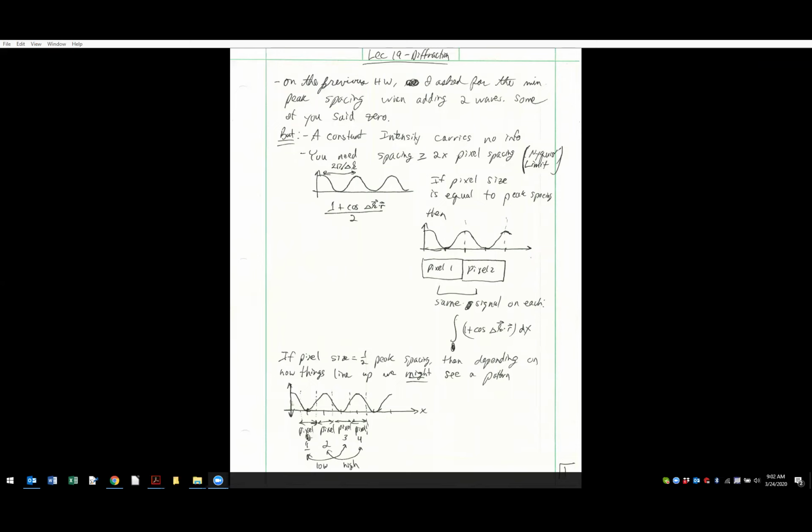And it turns out that this goes to a more important point about what is the optimal pixel size. What is the largest pixel size you could possibly get away with? And in general, smaller pixels are better, because even if the pixels are so small that you're not getting much signal on each individual pixel, you can always add up the signals from multiple pixels. You can always start off with something that's very fine-grained and then build up to something that's coarse-grained. But there is a maximum pixel size.